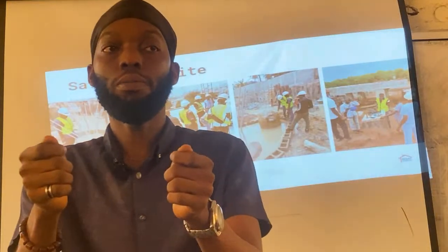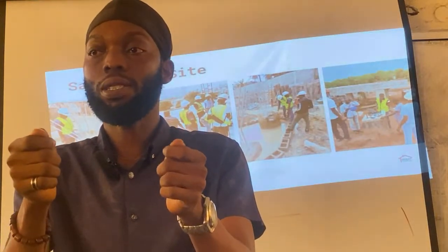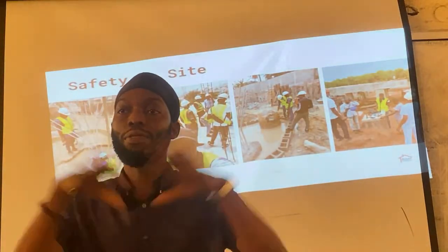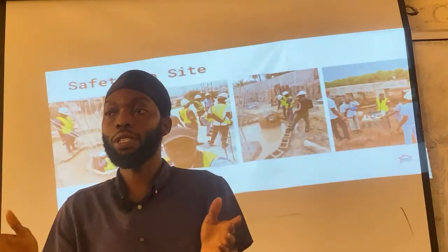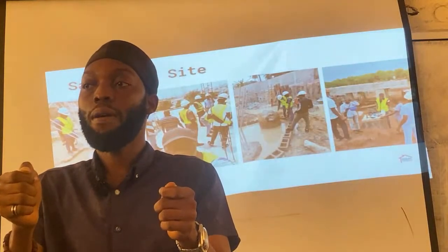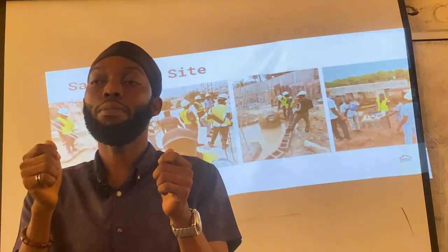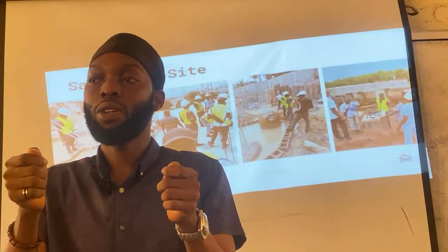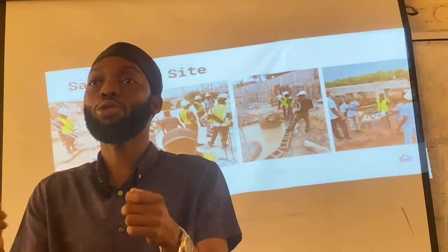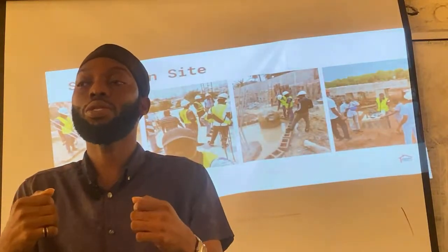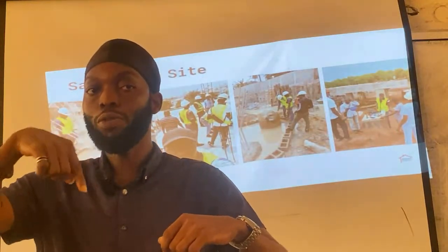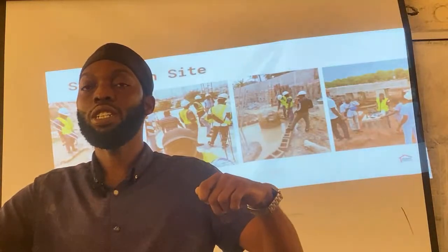Then you put your transducers on the structural element to test. But assuming you did not use any couplant or any membrane to eliminate the voids, you understand? And you put your transducers, it will definitely affect the readings, because the transmission path will change, because there are voids around. And in your structural element also, when testing through the direct method, if there is a void in the middle of your structural element, it will increase the transmission time.